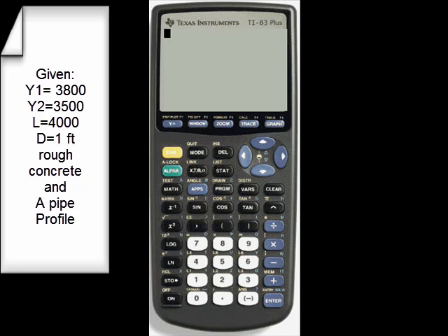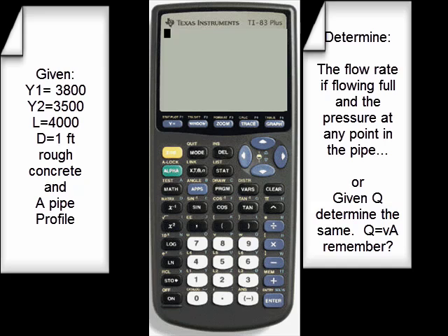In other words, it's going to use up essentially all of its energy along the pipe except for what remains in the velocity. You do this by writing Bernoulli's equation, understanding that head loss is equal to FL over D times the velocity head times the length. But in a program, you basically mostly just sketch this out, and you're given a program Bernoulli's on this calculator. Now, Bernoulli's is going to need some inputs. Those inputs being your friction factor, the head, the length, and the diameter.